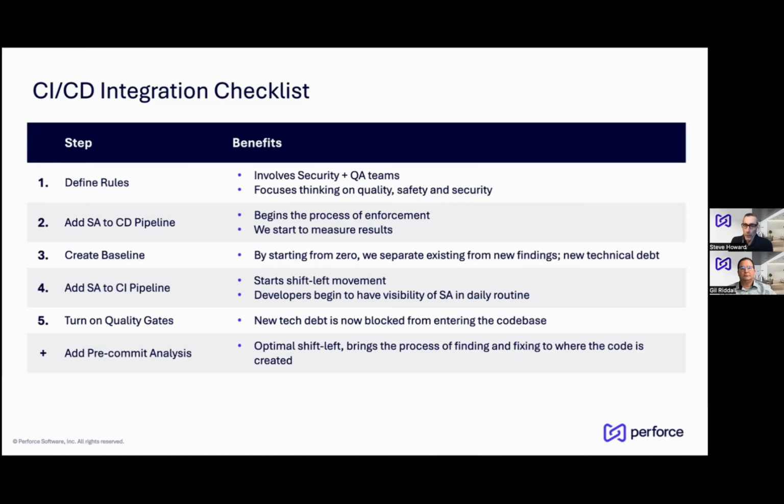Are we going to enforce all of them? Are we going to enforce just the higher severity rules or the mandatory rules from MISRA and the required rules from MISRA and not the advisory? That's a decision we have to make as a team centrally, because we have to pick an appropriate level for the project that we're working on. But all of that helps us to focus, of course, already on the quality, the safety, and the security.